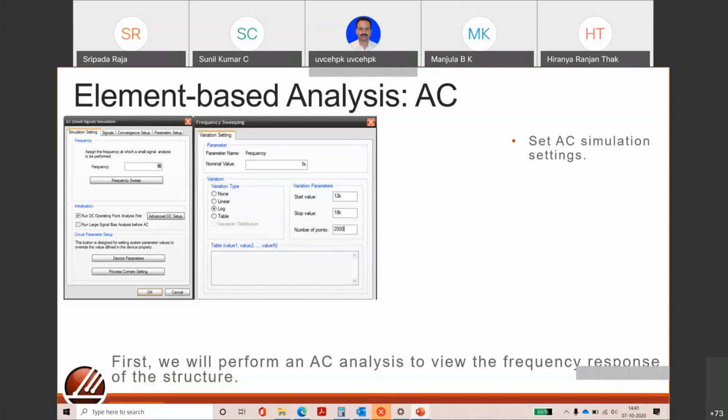We want to see the natural frequency because we need to see the operating condition. In case the gyroscope has to work at 200 kilohertz, we have to see what the natural frequency of the device will be. Remember that the device is not operated at natural frequency, it is always operated close to natural frequency.